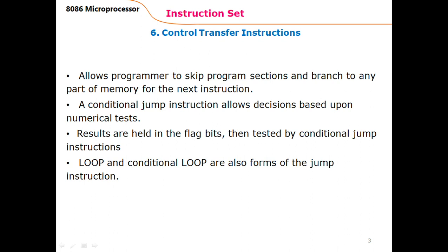So normally the microprocessor executes instructions of the program in a sequence, starting from the first instruction. Each time an instruction is being executed, the microprocessor maintains the address of the next instruction to be executed, which is next to the instruction currently being executed in the program, and this order is set by the programmer while writing the programs.